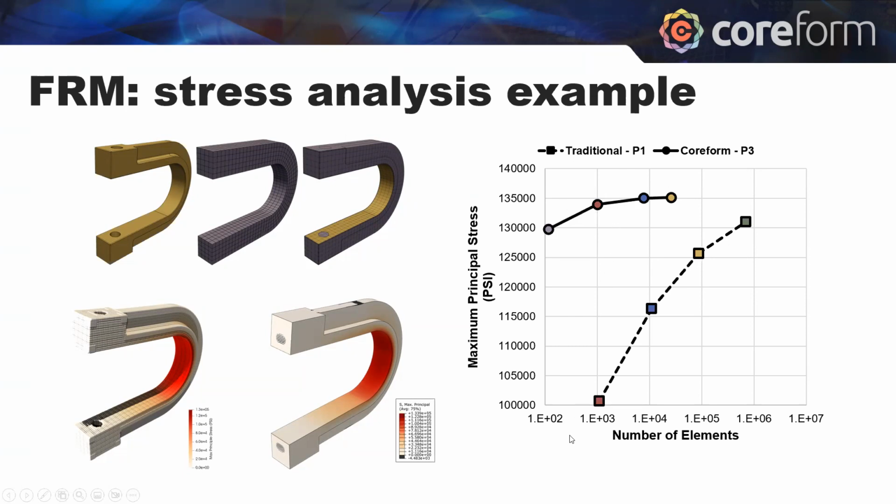And if you compare to traditional FEA approaches, where traditional FEA approaches are predominantly linear hexes, especially for nonlinear problems, you can see that we're able to essentially converge to a solution with several orders of magnitude fewer elements than might otherwise be required.